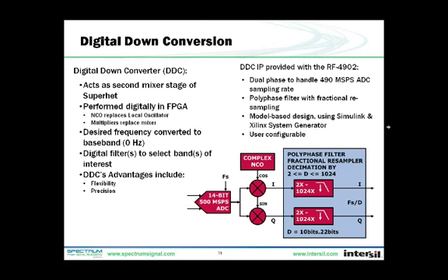It uses dual phases, or odd and even, in parallel. The ADC sample rate is too high for the DDC to process all the samples sequentially, so we have to break them up and use parallel techniques to run them through the system. It uses a polyphase filter with an integrated fractional resampler that has the advantage to give you almost any desired output sampling rate, including fractional rates.